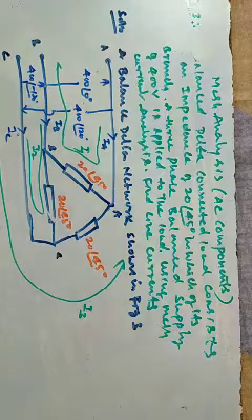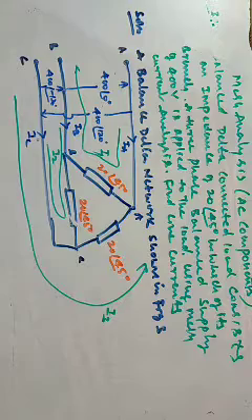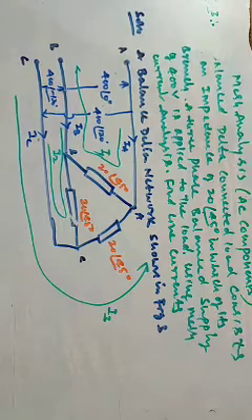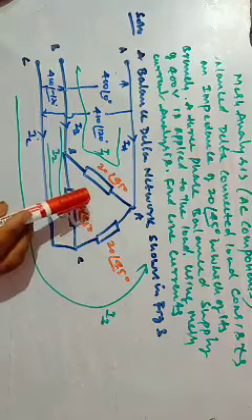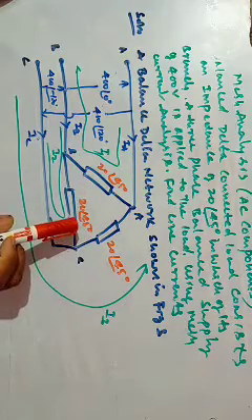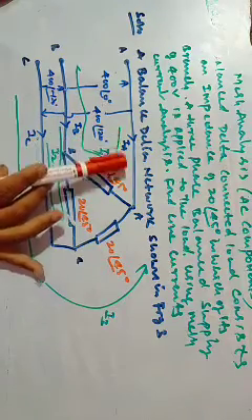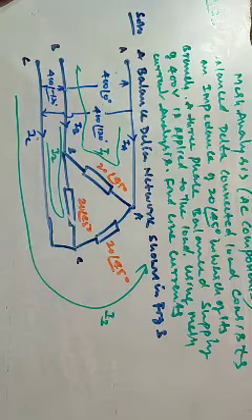See, the question is three phase of amplitude 400. So we'll have the three voltages: 400 at an angle of 0 degrees, 400 at an angle of 120 degrees, and 400 at an angle of minus 120 degrees. In delta form, three impedances of 20 at an angle of 45 are connected. Here it has asked to find the line currents. Line current means current through the line; IA, IB and IC are the three line currents.